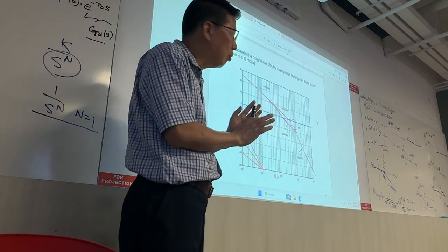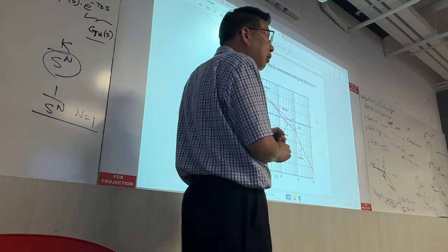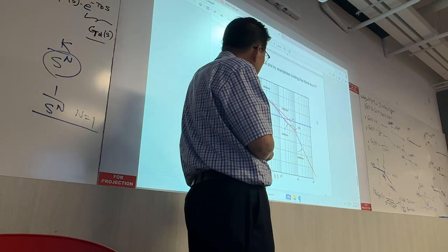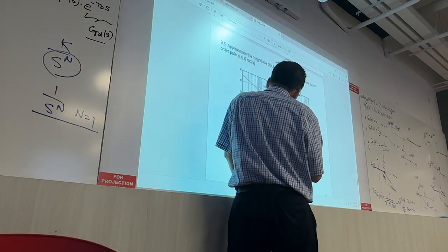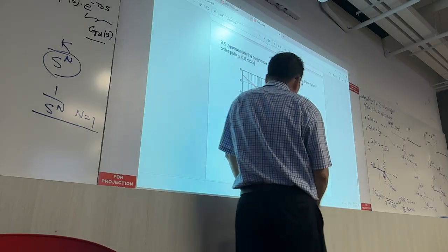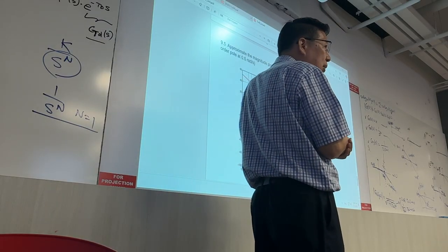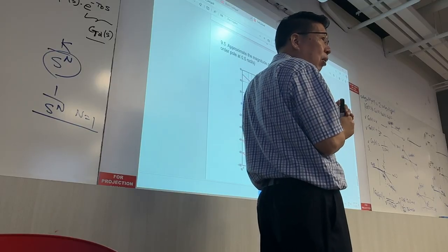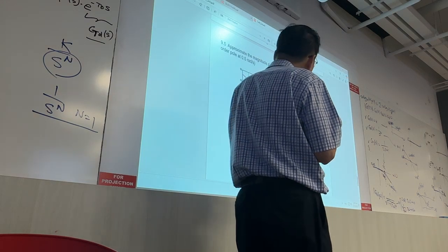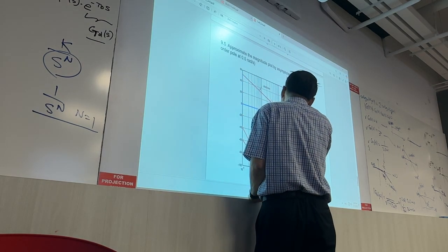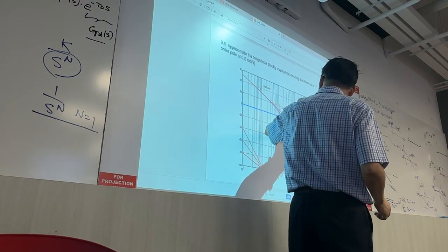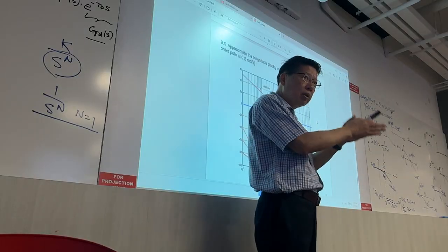Now here there's no unique solutions. Different people have different answers. Okay. It's all right. So long as these lines fit in the correct order as we did the analysis, we have some hint on the structure of the transfer function, and some corner frequencies are already given. Okay. So we get these red lines, and these red lines have intersections. These intersections will give us the corner frequencies.